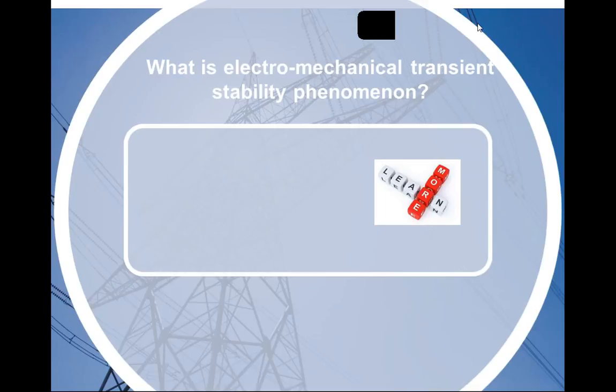What we are concerned with in this problem is the simulation of electromechanical phenomena. That is, phenomena that occur due to electromechanical disturbances and that have a transient duration in the range of seconds. Those phenomena can cause problems with the stability of the power grid.